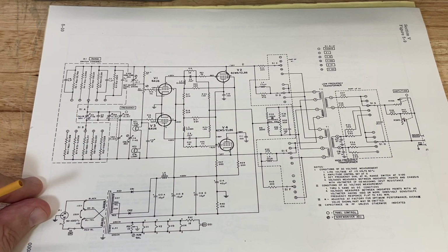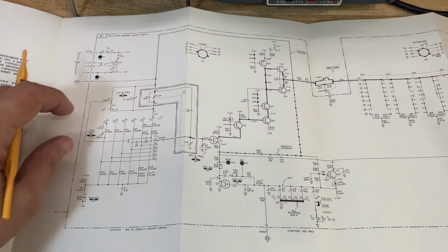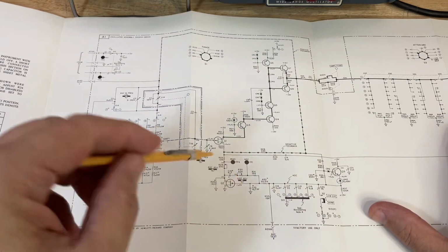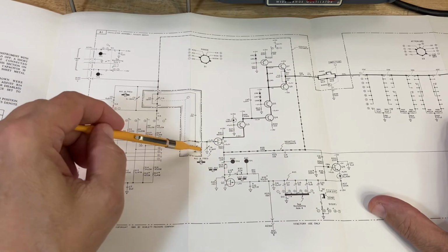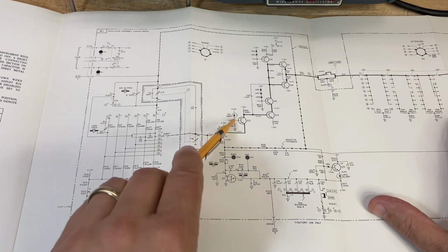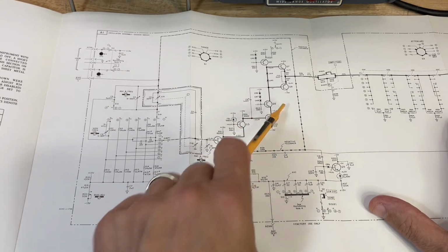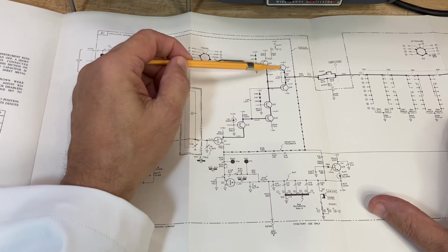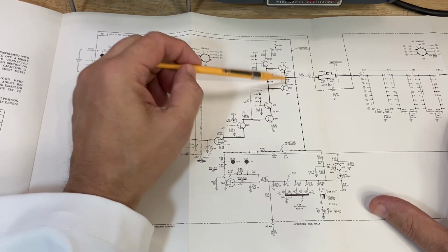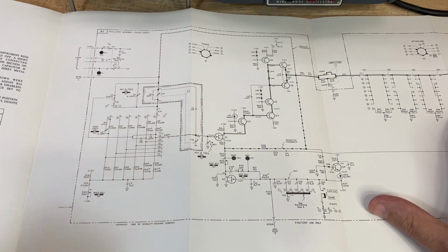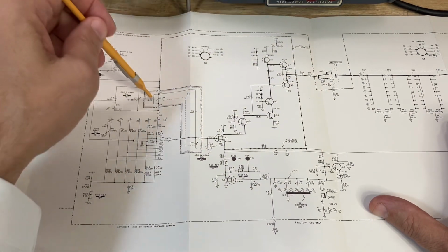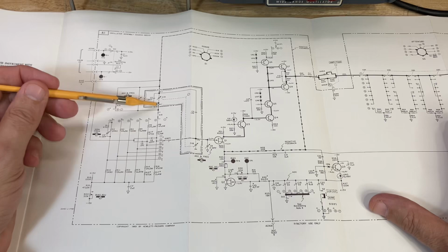Let's take a look at the 204C. Okay, here's the schematic of the 204C. Now, of course, there are no tubes, but there are also no op-amps, no chips in this instrument. It uses a FET on its input for high impedance input, and a series of transistors to do the amplification. We have a totem pole output stage here, basically emitter followers, the same as the cathode followers in the 200CD. Okay, we have positive feedback through that one leg of the Wien bridge.